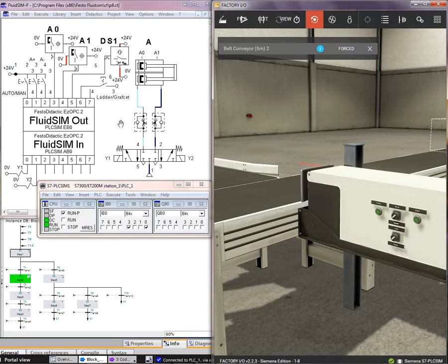I will describe it. In this circuit we should use a special 5/3 directional pneumatic control valve with 2 magnets and springs, of course. You can see the special cylinders with 2 shafts and flow control valves with check valves.